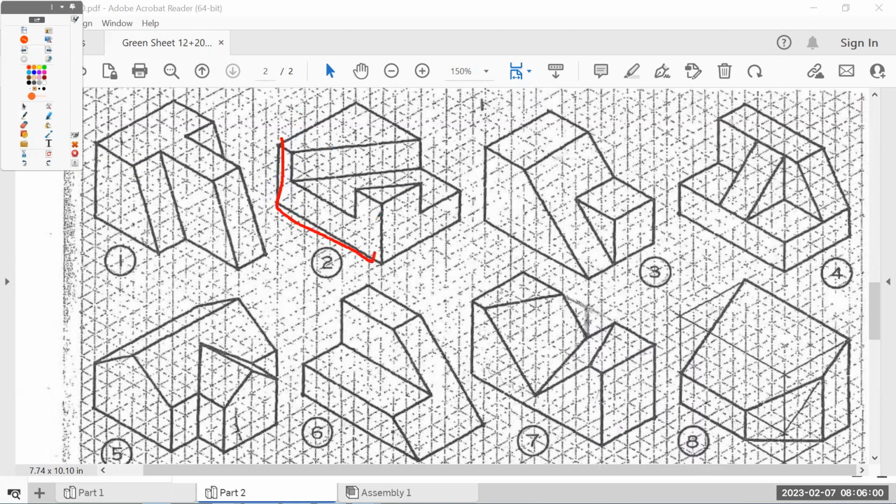Start with our big chunk of marble and then cut away what we don't want, which is just a single sketch. From the top, we can draw this shape and then cut extrude it down to, which is what we're going to do.